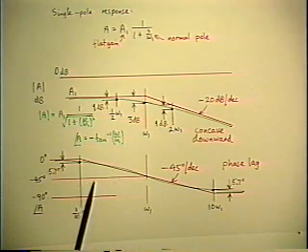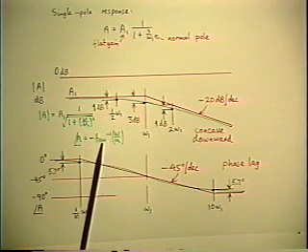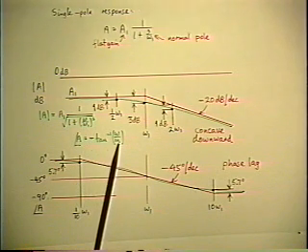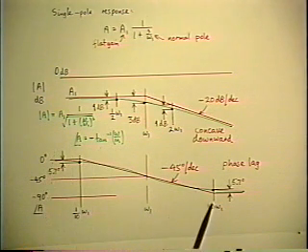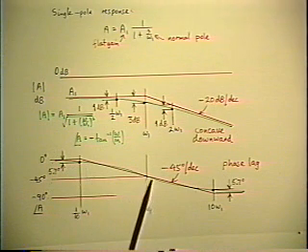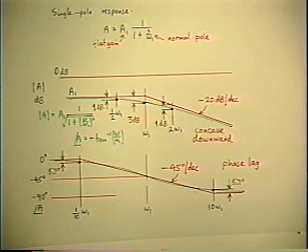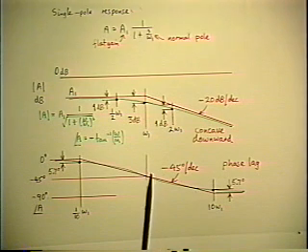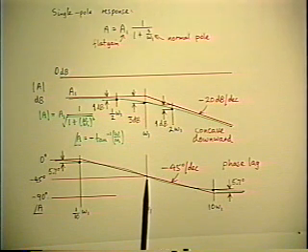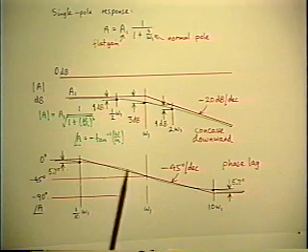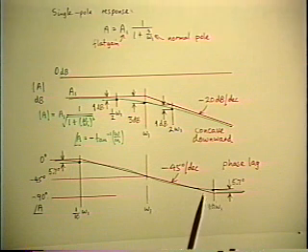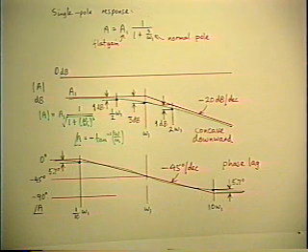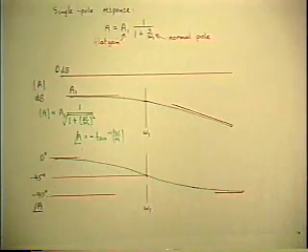So we're reduced now to actually plotting the function, the arctangent function. And we typically choose linear degrees versus log frequency. And again, interestingly enough, the function turns out to be anti-symmetric around the corner frequency. That is, the shape of the curve, the green curve below the corner, is exactly the same as the shape above the corner, except reversed and inverted. So that much of the picture is what we have.